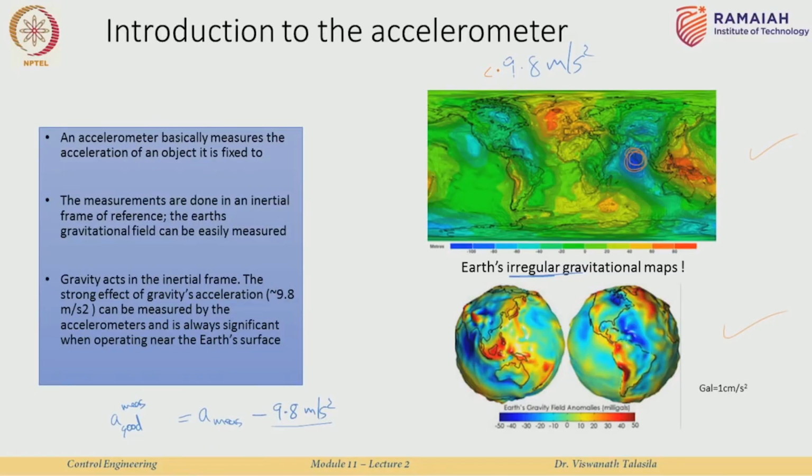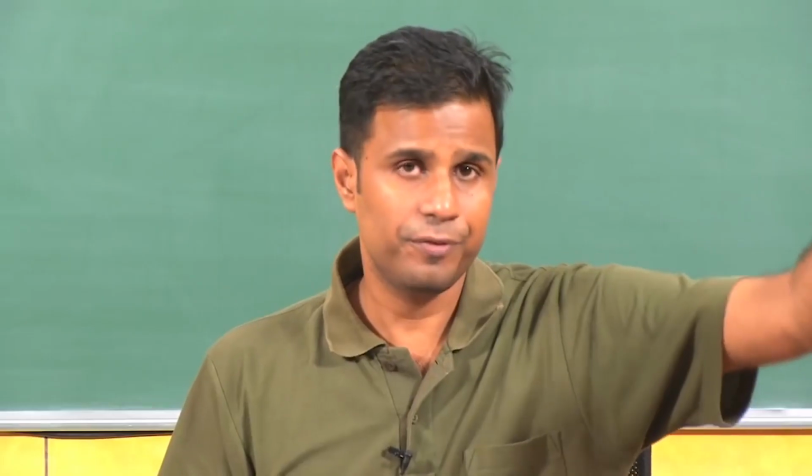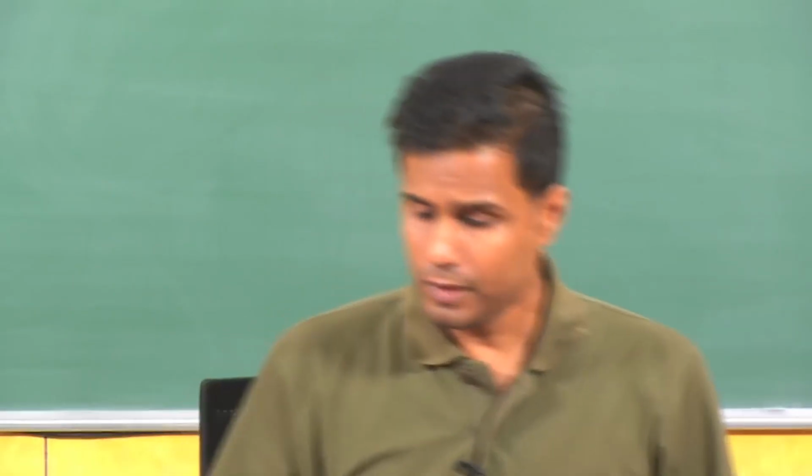So, now this is another problem, right? You need to compensate for this, but you cannot do it directly unless you have this Earth's gravitational field data with you, right? So, really professional navigators, they always compute the latitude, longitude, altitude of where you are on Earth, all right, and then they subtract out the corresponding gravitational acceleration from that particular place, okay.